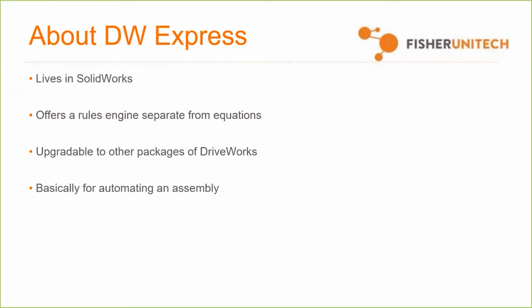It's basically for automating in assembly, so it's not going to do a whole lot more. It's going to let you automate your custom properties, automate dimensions and features, but not much else. And you're creating and storing copies. So I like to think of it like a Lego bin. You basically have a Lego bin, you throw a bunch of parts in there that you can use for later. You take copies of those parts, you drive them to different values under a different file name, close them down, and essentially you've made a pack and go of a different size.